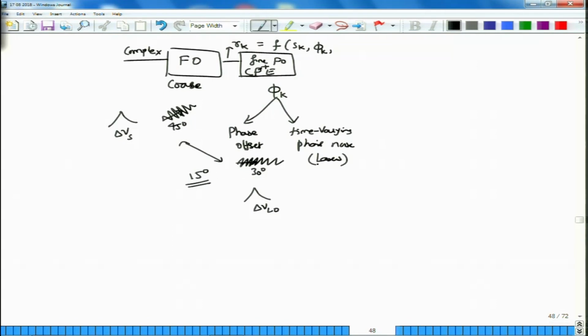The lasers that you have used will introduce this phase noise, and you have to overcome or compensate for this phase noise by first estimating it and then compensating. Of course, the received sample will also be corrupted by noise, because I would have put the front end preamplifier before the receiver part. The amplifier is going to amplify, but it will also introduce noise into the system, and that noise will show up at the sampled output.